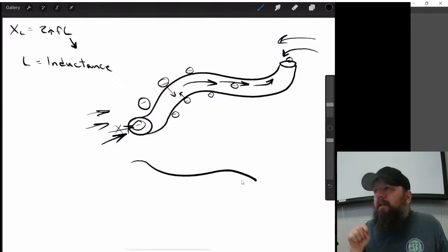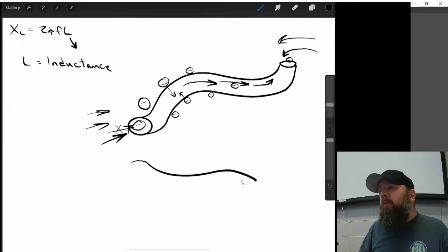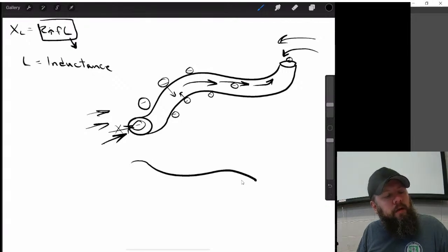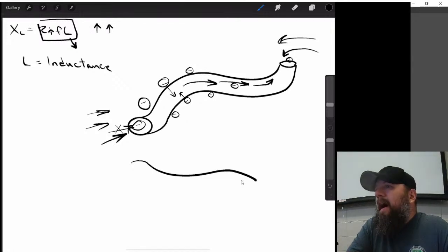So that was slow. Let's imagine that I'm pushing that button and letting it go once a second. That's 1 hertz. That's not exhibiting a ton of resistance to me. Remember, if you don't remember anything, remember that inductive reactance is a positive relationship. The higher the inductance gets, or the higher the frequency gets, the higher the inductive reactance gets. And inductive reactance we can think of like resistance in this case. Okay? Y'all cool?